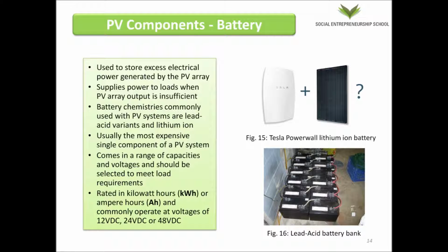Batteries are sized based on the power requirements of the electrical devices they supply and the number of hours of non-daylight operation. Many devices, such as electric motors and compressors in refrigerators, have surge currents on startup. Battery banks should be sized correctly to account for these surge currents.